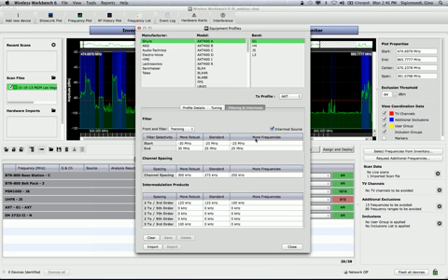And by personal space, what that really translates to are these numbers here that define the filtering and intermod considerations taken for each system. In effect, we've got 3 profiles for each one of our systems, each one of the bands of our systems and all systems, that define how much space is needed. And larger numbers equal more personal space, which equals fewer simultaneous channels on the air. So for all these systems, including these competitive ones, we've got profiles built that come with Wireless Workbench. In addition, if you're using wireless systems that we don't provide, you can build your own.